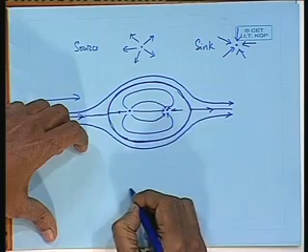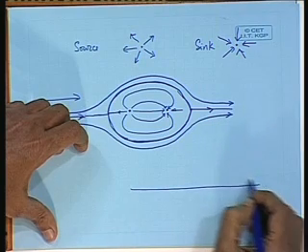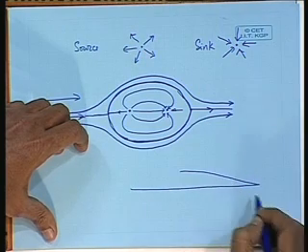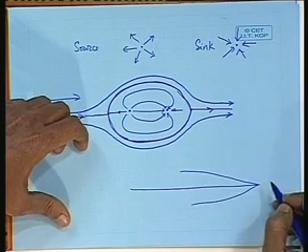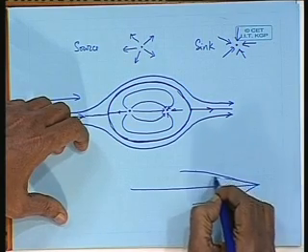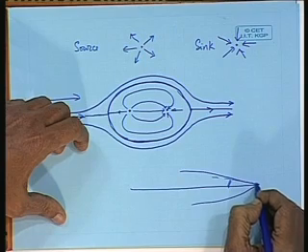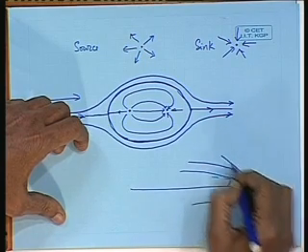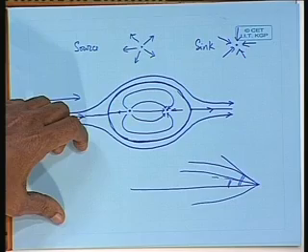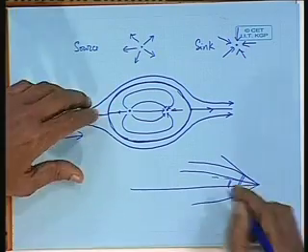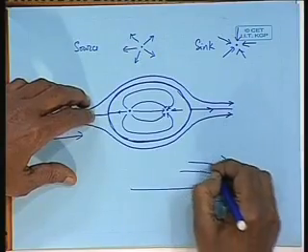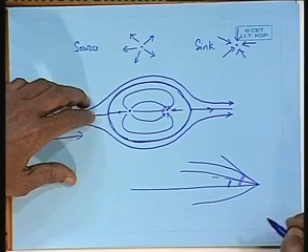Am I clear? Therefore, if I have a waterline like this, you see the slope here is something like this angle, and if I have a waterline like this, the slope here is this. I have two ships, one ship giving a waterline like this and another ship giving a waterline like this. Which one will give me better wave resistance? Obviously, the one with the smaller slope, that is wave crest will be small.